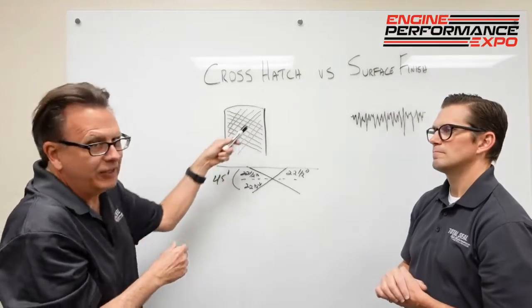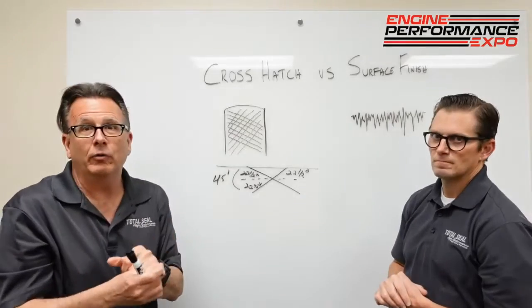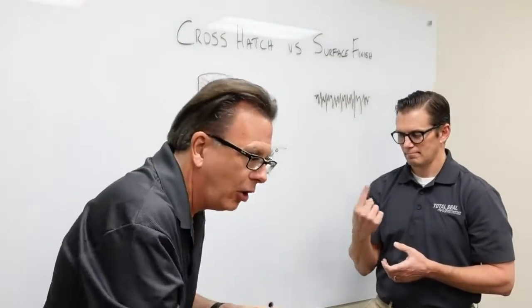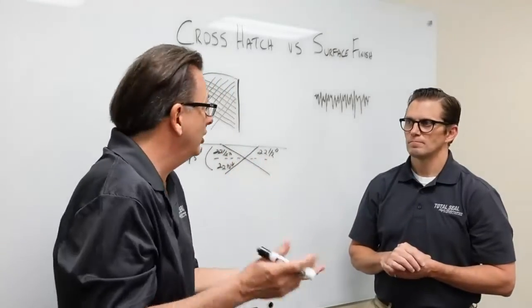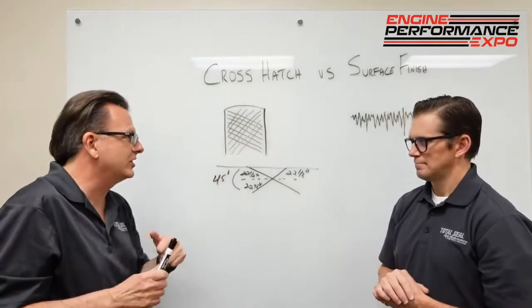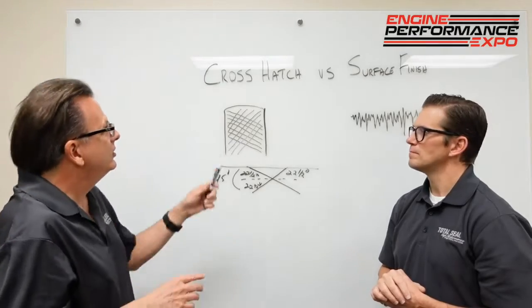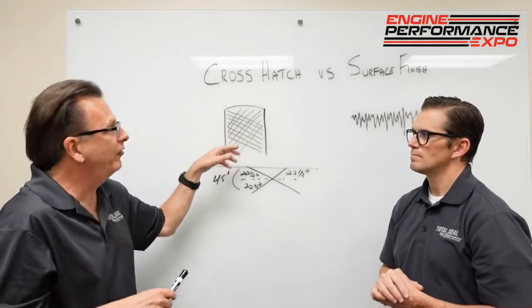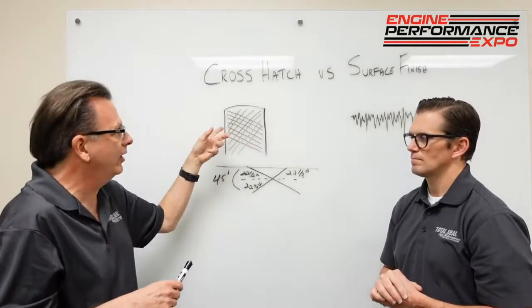What changes with these angles are, one, ring rotation speed. Rings rotate on the engine. They're on the piston, I should say. They're always turning, unless it's a pinned ring like a two-stroke. Right. We've got to obviously stop that, can't have it go over a port. So this is going to help determine ring rotation speeds, but it's also going to affect blow-by and oil migration.